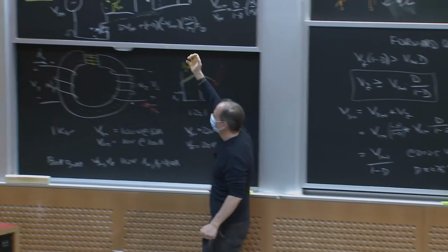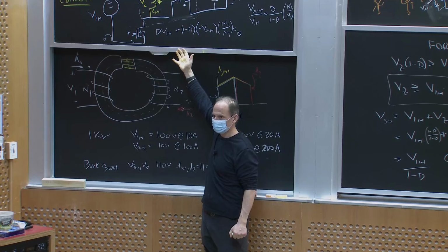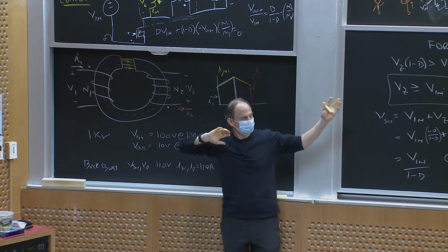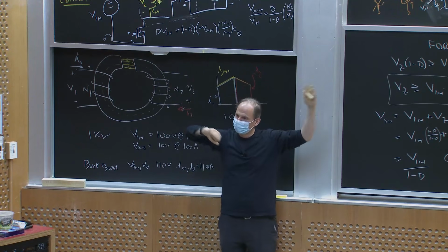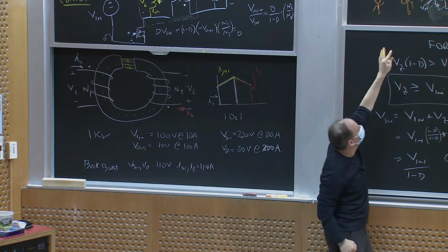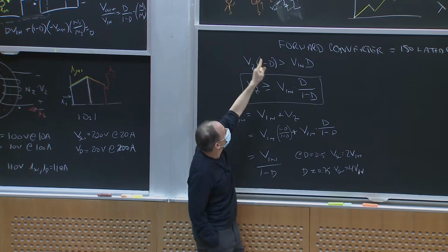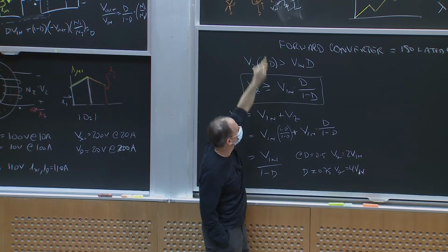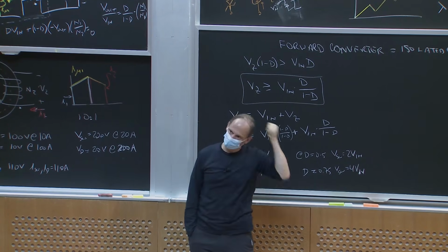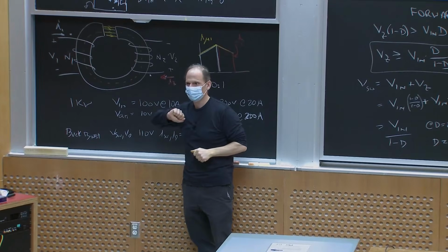The flyback converter is based on an indirect topology which has lots of energy storage. So it turns out that depending upon the design regime, a forward converter can actually be a lot smaller because, keep in mind, this transformer doesn't really need to store any energy. The only real energy storage element, which is sort of the size limiting element, ought to be that inductor. And that inductor is smaller than this flyback transformer.